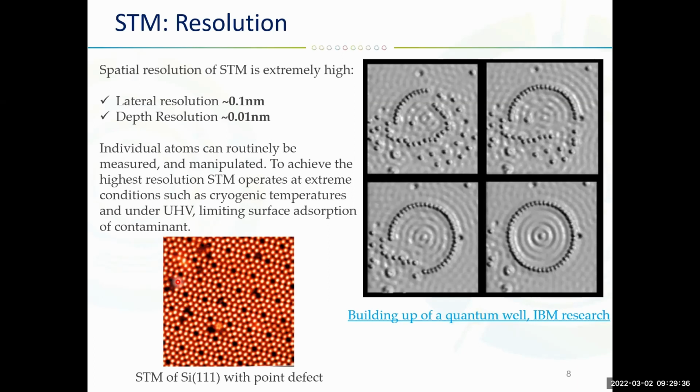So what are point defects like in real life? Typical point defects are impurity atoms in a pure metal, or vacancies or self interstitials. Why do we need to know this information? Because we need to control these point defects in semiconductors. If a semiconductor does not have any defects, then it is not a semiconductor. It is very important for the fabrication process to control the concentration of these defects. That's why STM is used in this process.